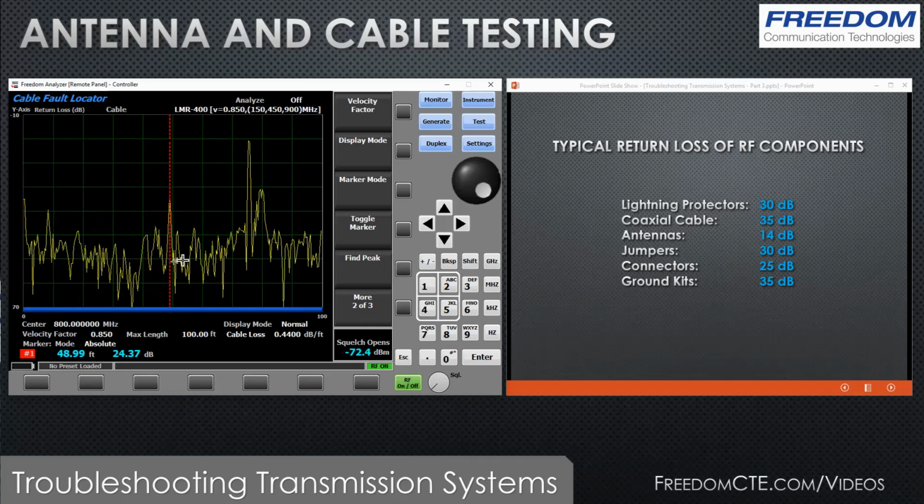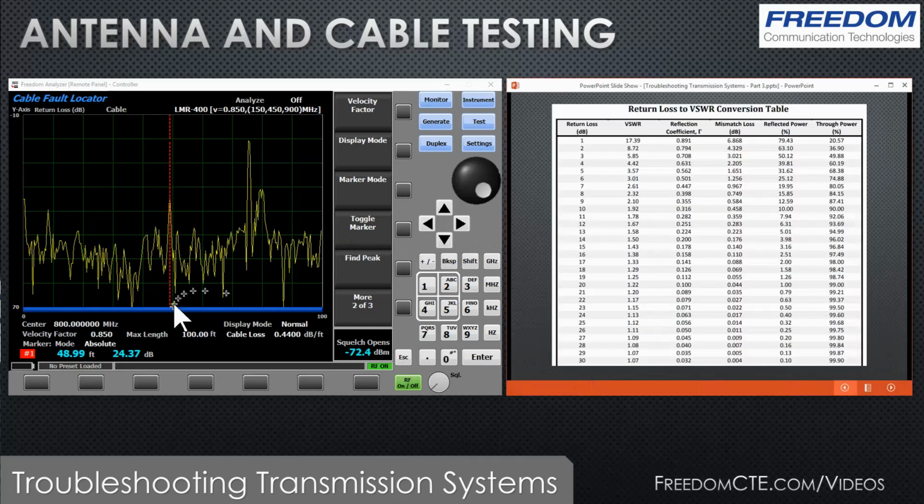But you can see very clearly where all the discontinuities are. You can see the good cable is down here, and you see discontinuities. And again, you might now wonder, what is the equivalent to 25 dB? If I look at the chart, it is 1.12 for a VSWR number, which means that only 0.32% of the power is being reflected, so probably not a major concern.